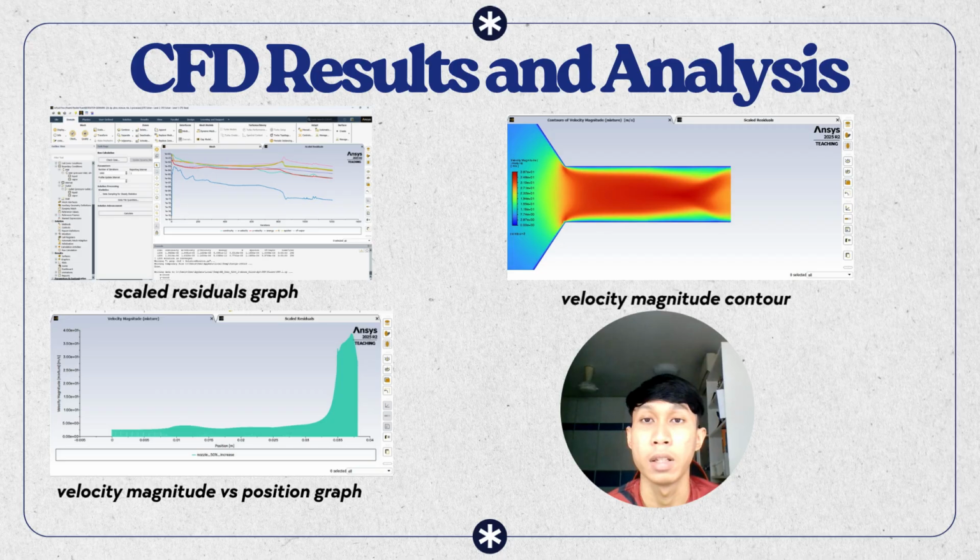For the last part is the velocity magnitude versus position graph. For the decreased diameter, the velocity remains low at the inlet but increases very sharply as the fluid approaches the nozzle throat. However, for the increased diameter, the velocity increases more gradually and reaches the lowest maximum value because the larger flow area reduces the acceleration of the fluid.